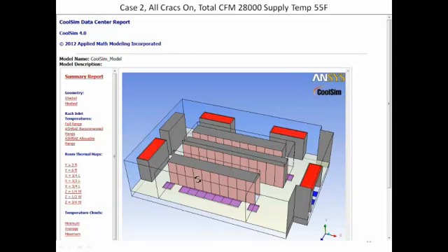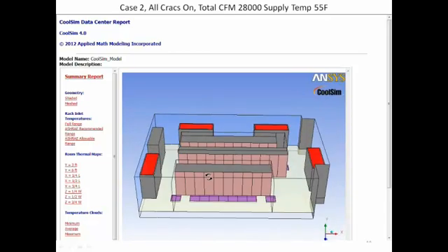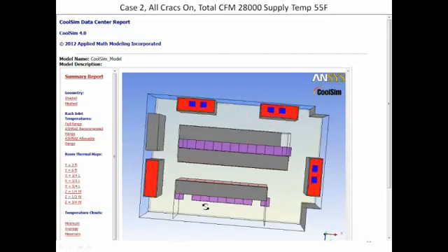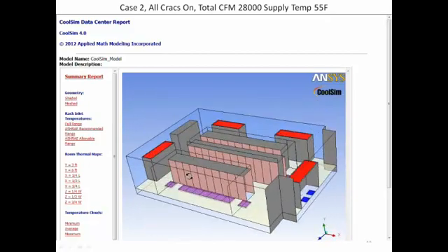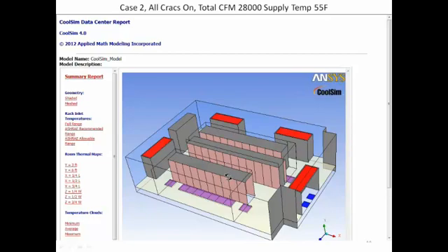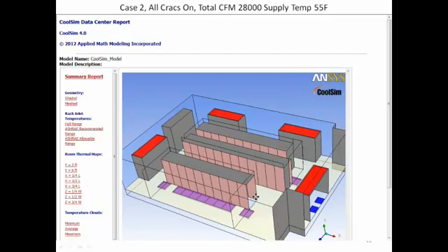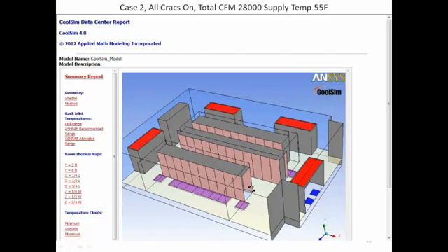Now, what they were telling me in this particular room is the customer was very concerned, and again, you have people in these rooms. These are customers' equipment. So the customers are very sensitive about cooling, and they wanted to make sure they had enough. So they overdid it. 4 units in one room. But the irony is that it actually doesn't improve your reliability. It actually makes it worse, because what happens is these CRAC units run on and off and cycle up and down, and as a result, they wear out quicker.